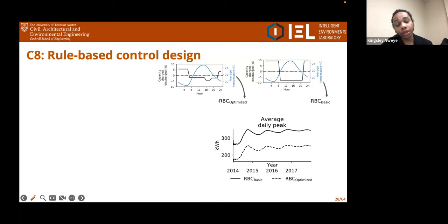And since we use a heat pump to provide the cooling energy to the thermal energy storage, and the coefficient of performance for heat pumps improves, at least in the cooling scenario, if the temperature is lower, it makes more sense to provide the cooling energy at the coolest time of the day. And then on the flip side, we are discharging at a higher rate when we expect the peaks to occur, between I think 4 to 6 p.m.